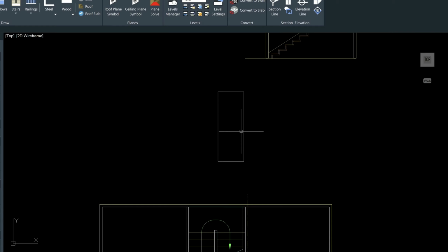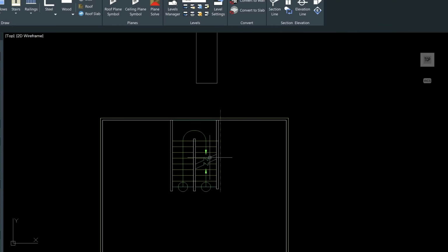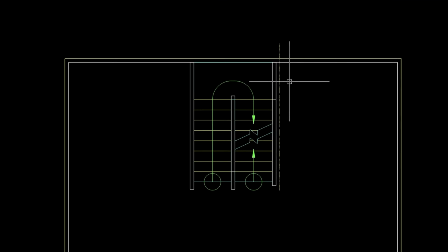There's a couple more pieces that we need to extrude as well. But let's talk about the floor openings. So as you come up this stair, there's going to be a rail here. That rail needs to separate itself from the edge of floor above. Otherwise, the rail is going to just hit the floor. And so I was thinking about a distance of 1'6" away from this rail here, where the opening will take place.